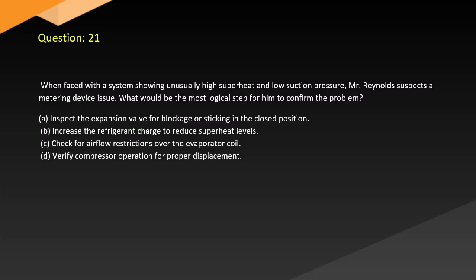A. Inspect the expansion valve for blockage or sticking in the closed position. B. Increase the refrigerant charge to reduce superheat levels. C. Check for airflow restrictions over the evaporator coil. D. Verify compressor operation for proper displacement.